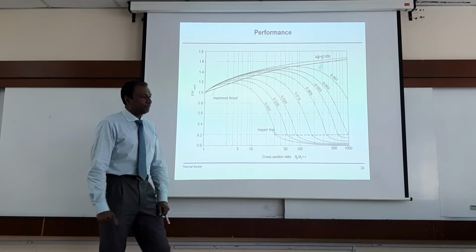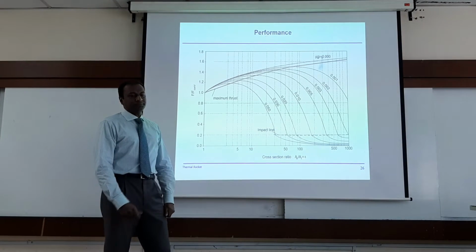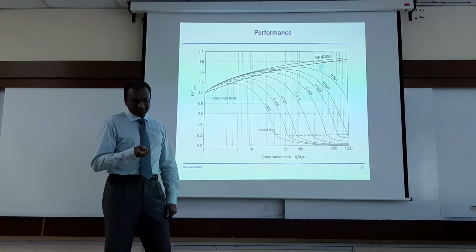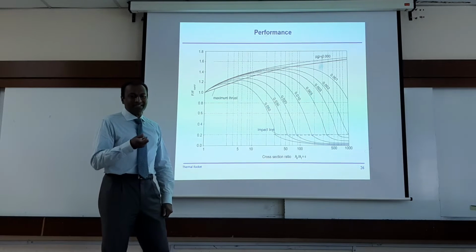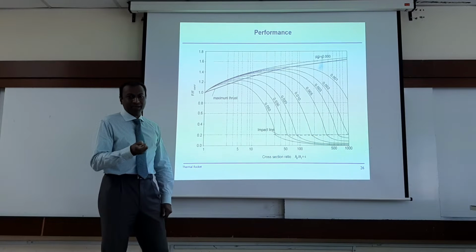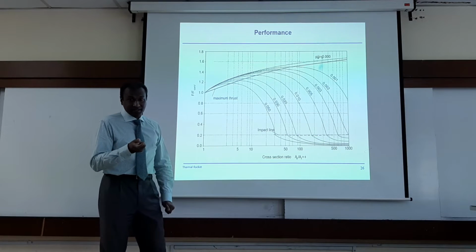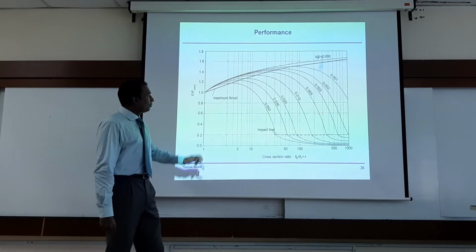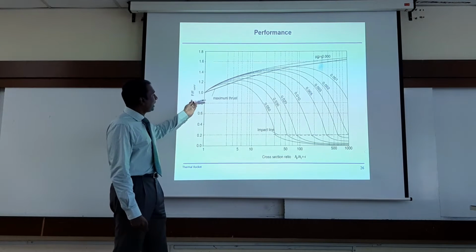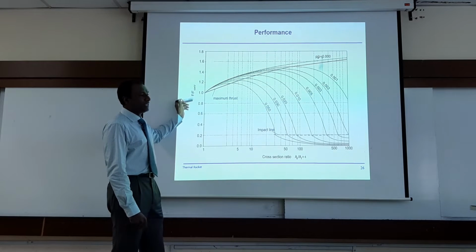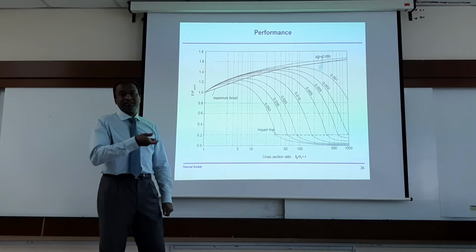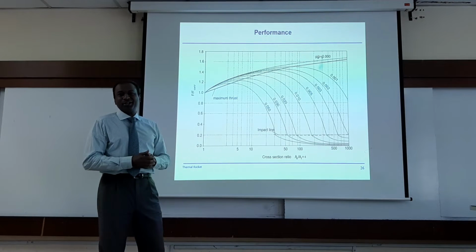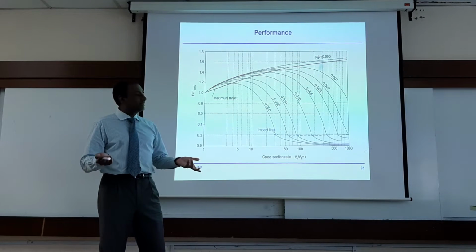So which means that if you have a gas flow into the throat, do you want the same amount of flow, or rather the same velocity, to be out? No, you want more. That's what it means here. So all we want to do is make sure they are not the same. If they are the same, practically what you are saying is that the convergence and the divergence forces are still the same. So that is not the idea of designing an engine.